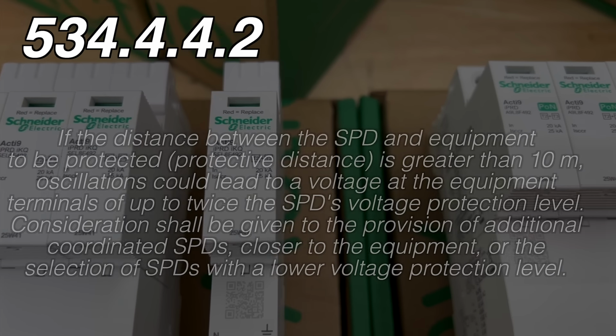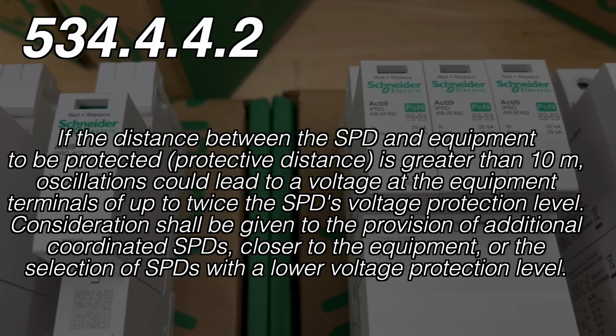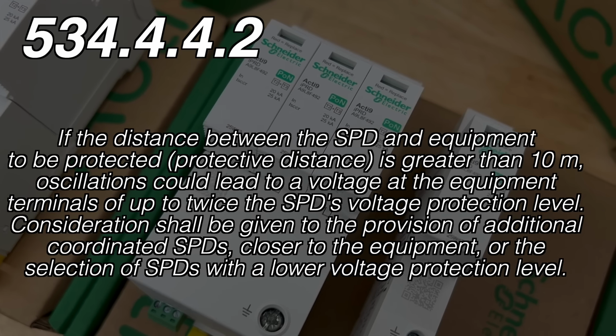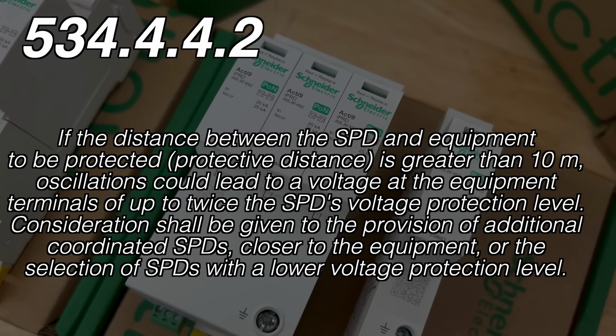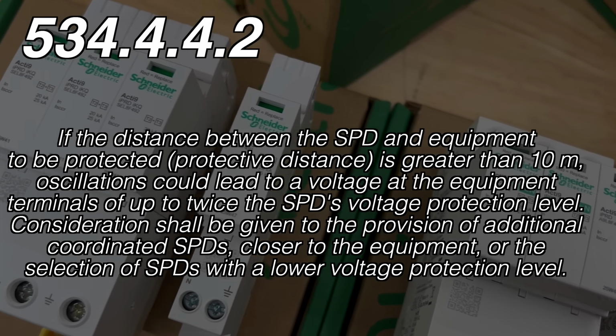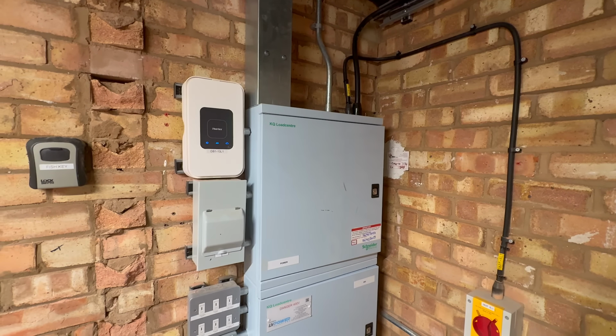534.4.4.2 states that if the distance between the SPD and the equipment to be protected exceeds 10 meters, oscillations in the conductors can result in a voltage at the equipment terminals of up to twice the SPD's declared voltage protection level. Oscillations? Okay, so what does that mean? Well, to understand that, we need to understand what happens to the cables during a surge event.